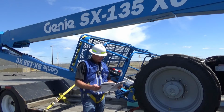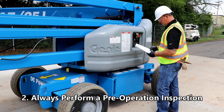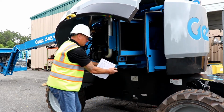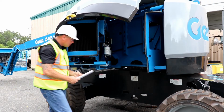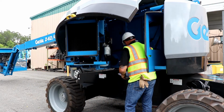It is critically important before you even get near the work environment or the machine to know what kind of hazards to be looking for. A second key concept for safe machine operation is the pre-operation inspection. This is important because very often you may not know if the machine has been damaged or modified or if it's been properly maintained. This visual inspection is designed to keep the operator out of harm's way by discovering if anything is apparently wrong with the machine before the operator performs the function tests.